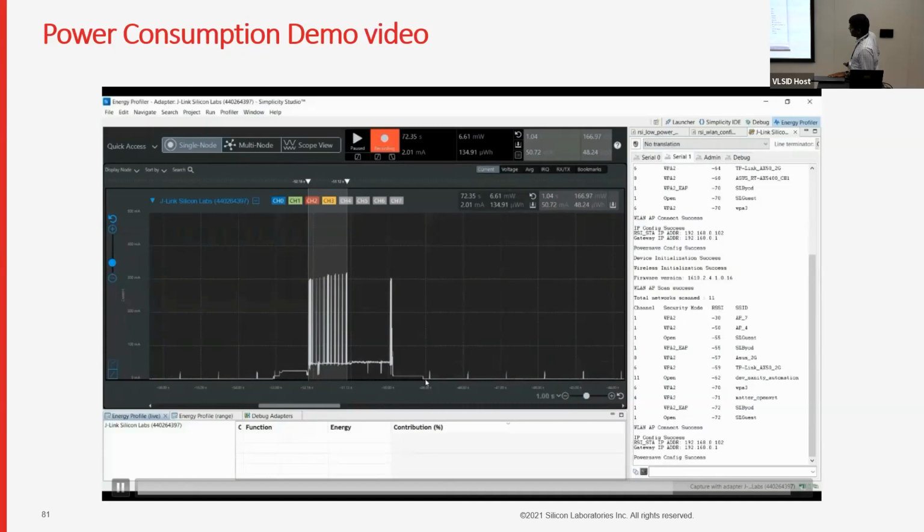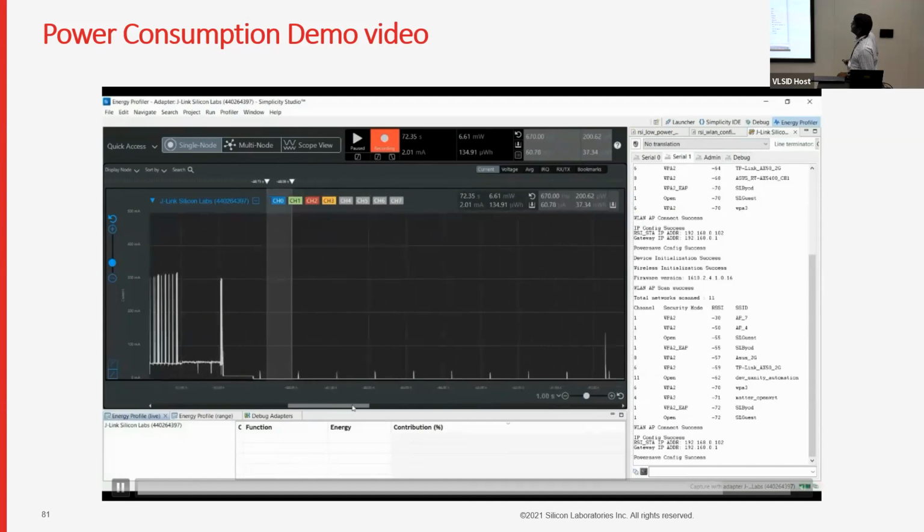And we can also keep the MCU in a low power mode. We have discussed EM0, 1, 2, 3, 4 modes, right? As Venkatesh mentioned. So that will even further reduce the power consumption to microamps. So this is that particular current. So now we see around here 60 microamps after this connection. So this is the average current consumption.